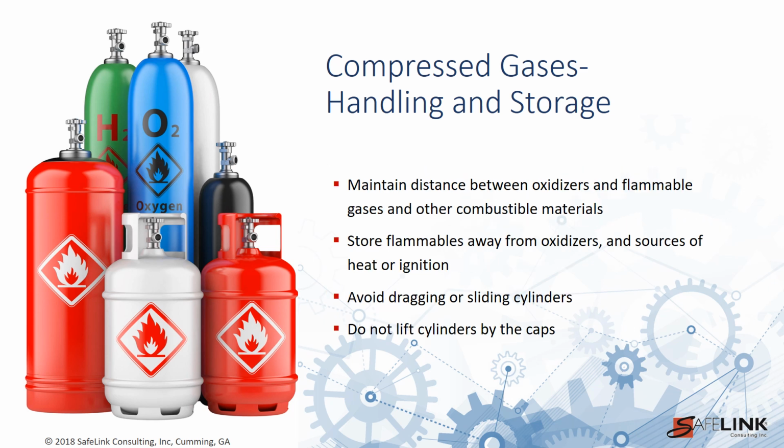Maintain a minimum of 20 feet between oxidizers and flammable gases and other combustible materials, such as oil or grease. Firewalls, such as a partition 5 feet high with a half-hour fire rating, can be substituted. Store flammables in well-ventilated areas away from oxidizers, open flames, sparks, and other sources of heat or ignition.